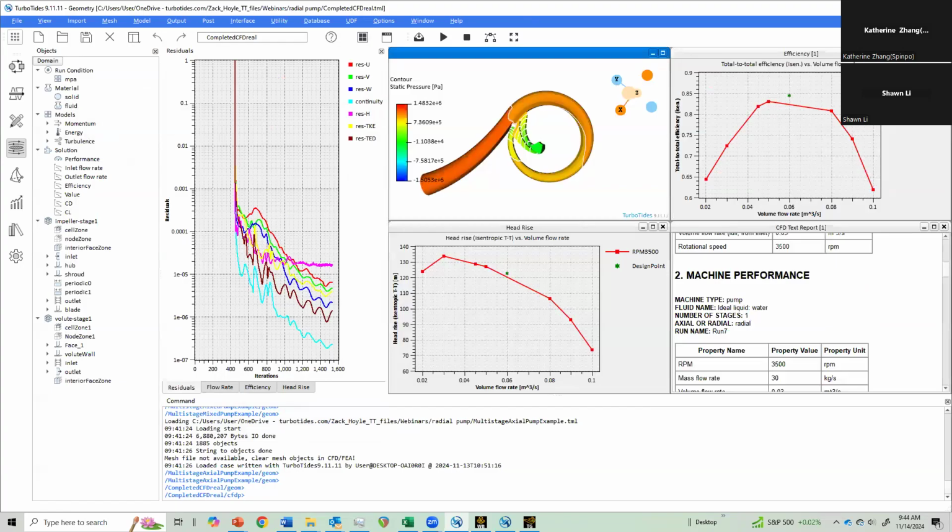So we're also moving on to one of the most unique aspects, and the last part of this demo, which is the data reduction. This is probably the most powerful and unique aspect of this program, where you can use these CFD results that we already have here to go back and calibrate our 1D, and then use the 1D model, which will now be accurate after calibrating, to make adjustments and not have to do time-consuming CFD.